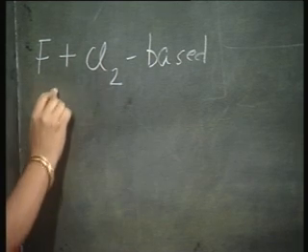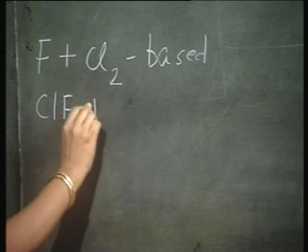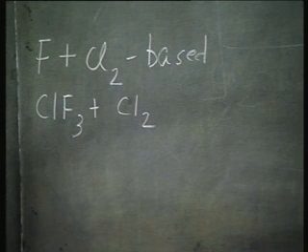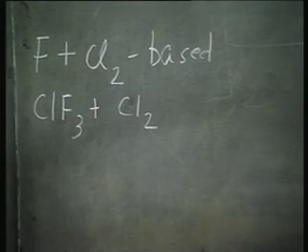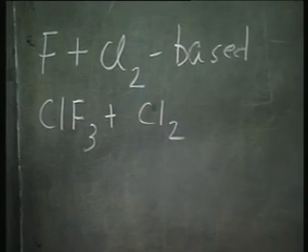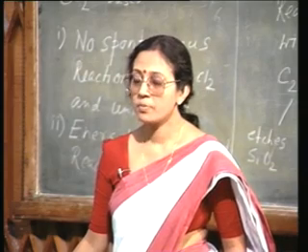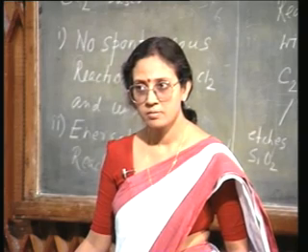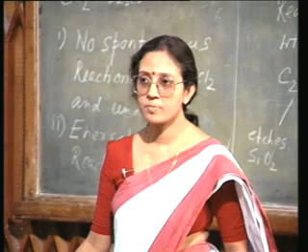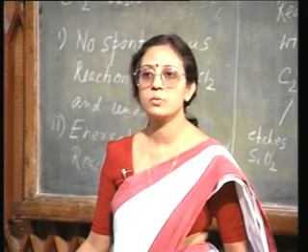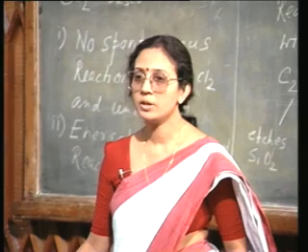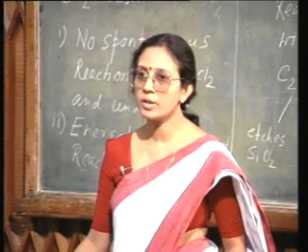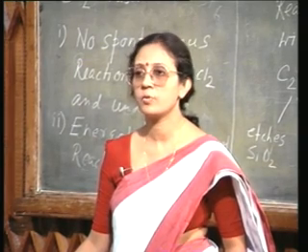Feed gas is going to be ClF3 plus Cl2. What you have is, you start with pure ClF3. So, pure ClF3 is going to give you most fluorine, okay. Mostly the active species obtained in a ClF3 plasma is going to be fluorine. So, the etch profile will be isotropic. Fluorine based etching, I am going to have isotropic profile.